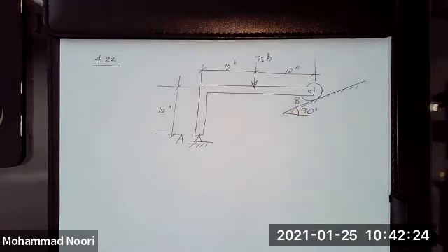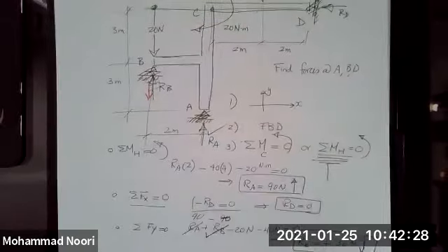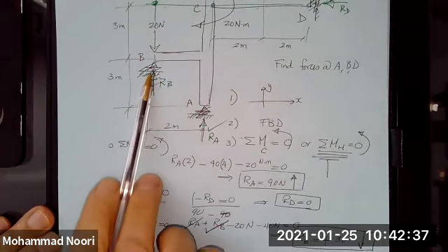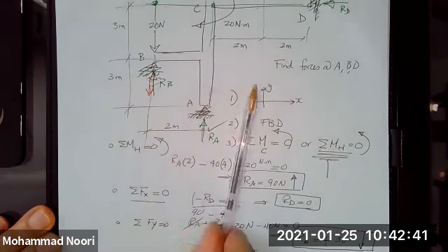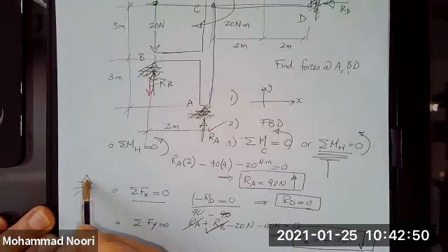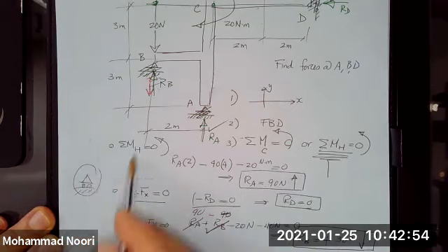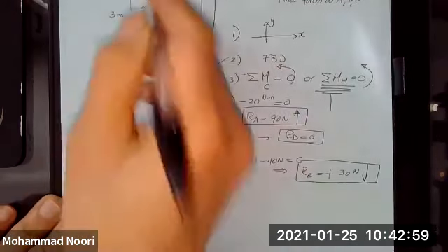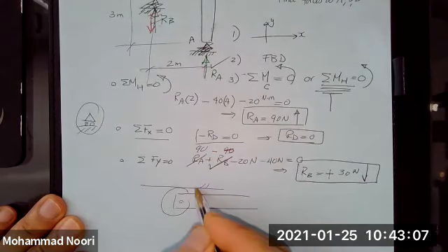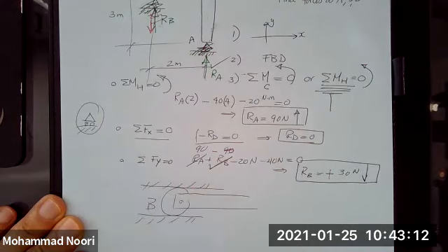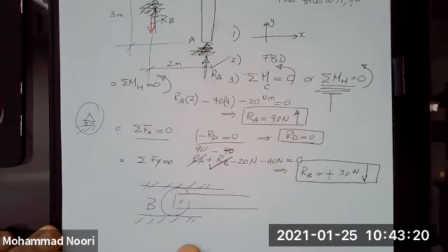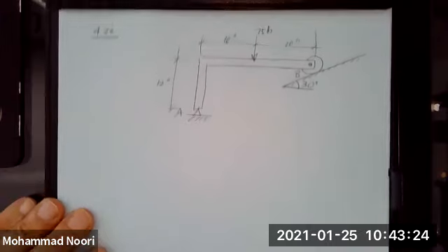Oh, by the way, I forgot, because this was a good question somebody asked in the other section. Although you didn't ask that question, it may be a good idea to go over it. The individual asks, how in the world, if this is a roller and you say motion can take place in this direction, then in that direction, but what you're showing me is something like this. So that means this roller can be lifted. This is just a symbol. What this means, for instance, is at point B you have a mechanism like this. So this is what that support B would be. You cannot move it in this direction. Motion is only allowed in this direction. But anyway, I thought that was a good question someone asked in the previous section.